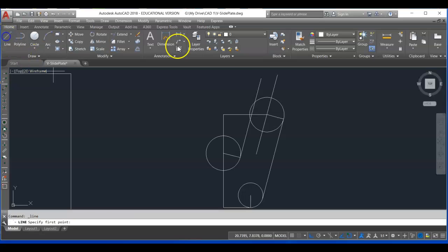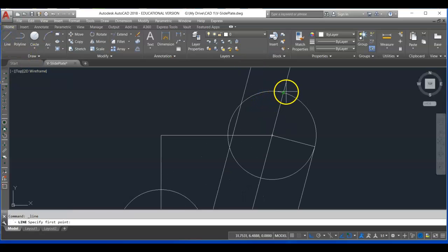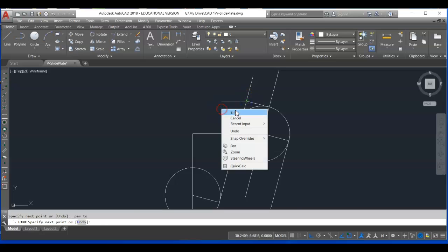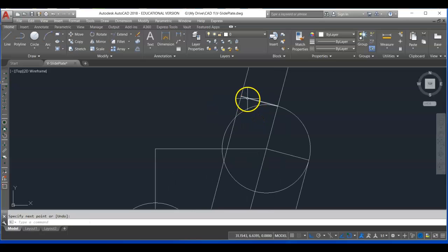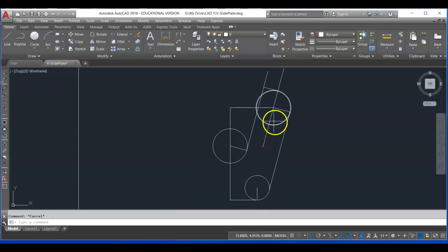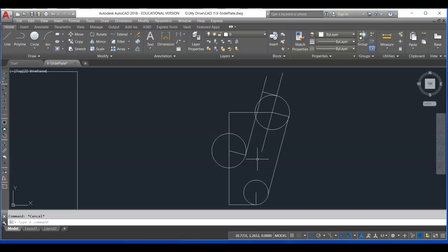So we're going to use this intersecting point here and snap over. And the drawing requires this to be 90 degrees. Well, 90 degrees is the same thing as being perpendicular. So we could go ahead and use a perpendicular snap. What that should be is this line and this line should have an angular dimension of 90 degrees. So that's the construction of the right side.